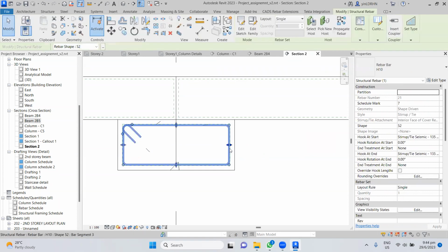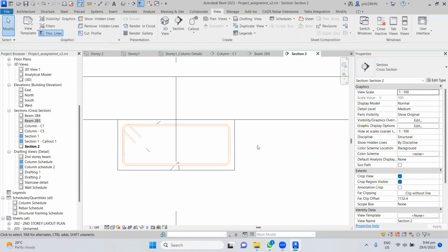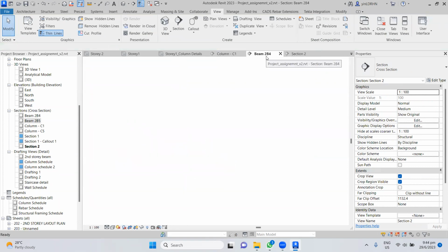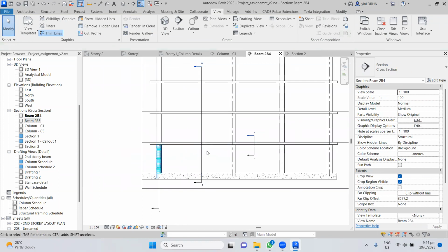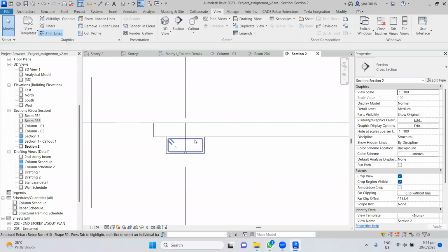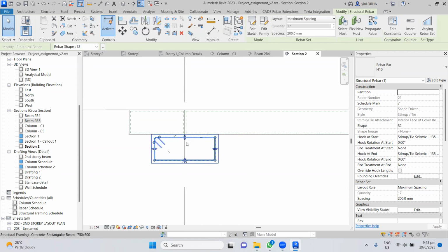Okay. So we brought the link already, right? Now in the section you produce a link. Okay, now this is a single link, right? So we had to multiply this one. I project spacing, create spacing 200, right? So you see that this link, supposed to be a full link, cannot be only here, right? Because the beam also is part of this one, right? So we had to move this one like this.